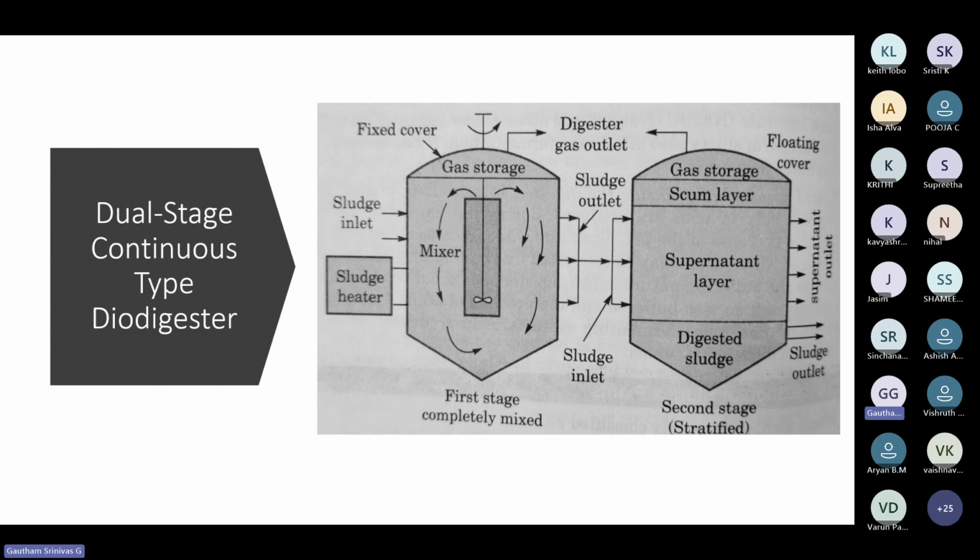But some of the stalk is floating on top because it is very light. It is still floating on top, and that is one issue with using agricultural residues, especially stalks, for biodigestion. That organic matter that floats on top is the scum layer.